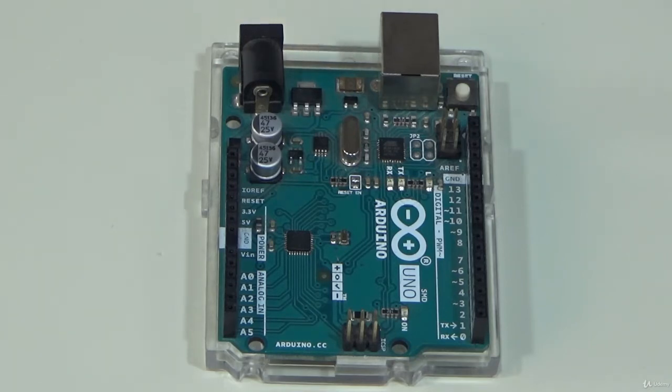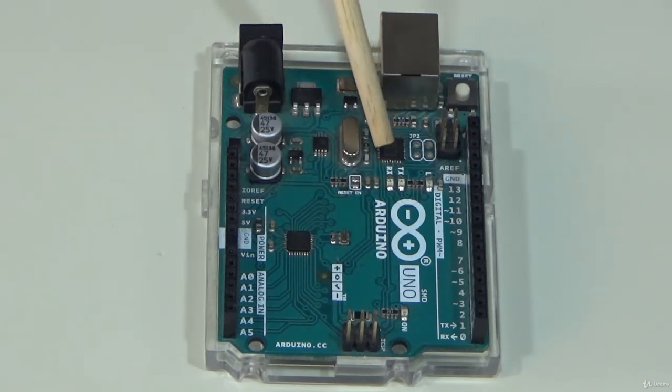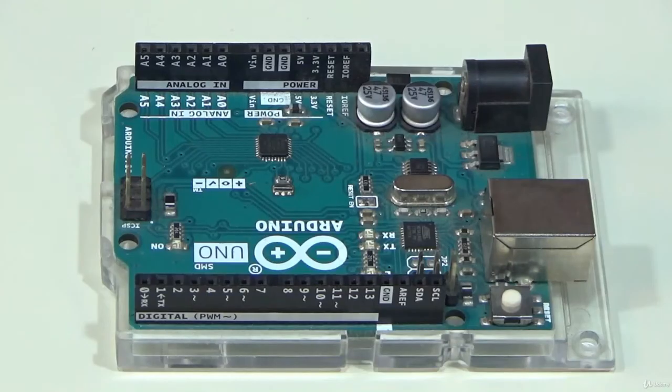And this voltage regulator is used when we are using an external power supply through this jack. If we connect an external power supply, then only this will be required. This is the external programming connection, which is called ISP. This is the USB UART bridge, which is used to convert USB signals into TTL and vice versa. This is the USB connector through which we can program the microcontroller through a USB cable.